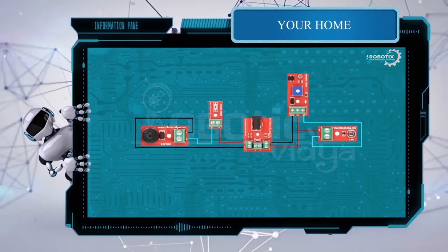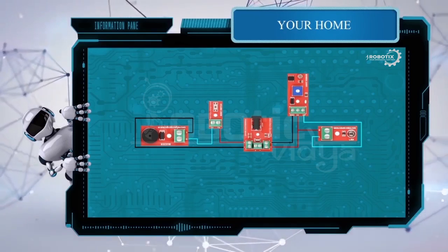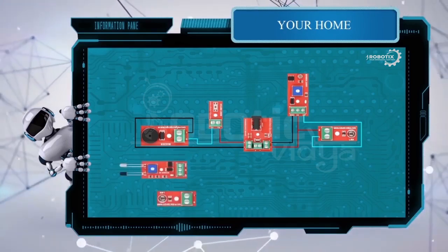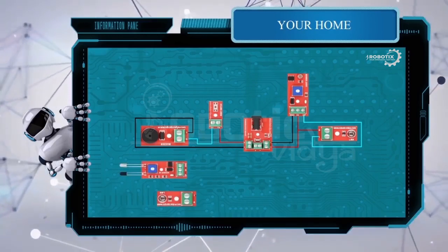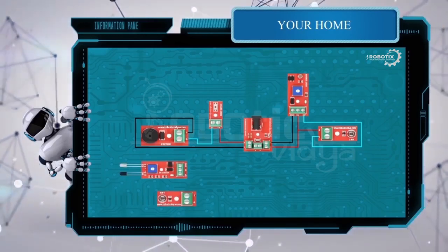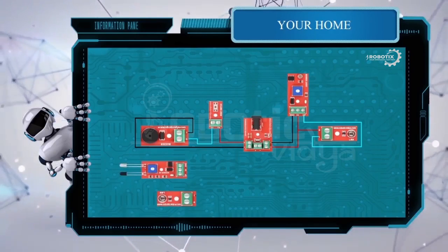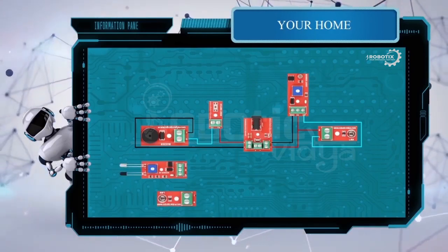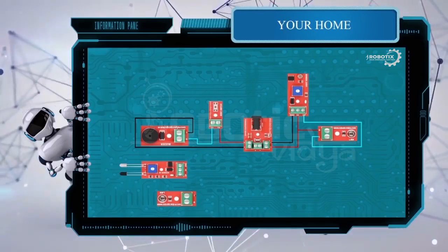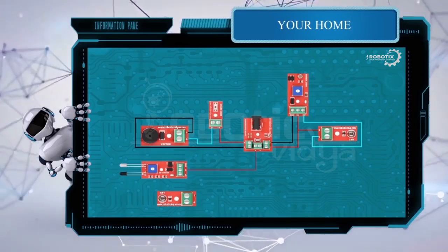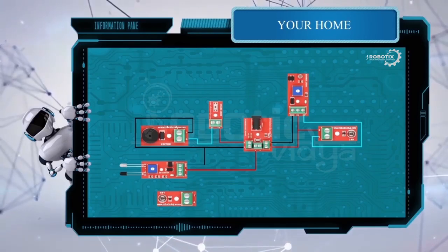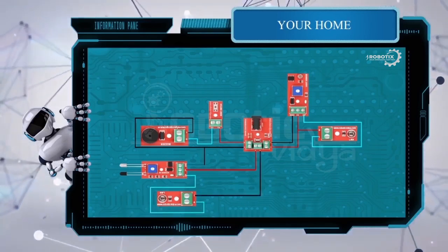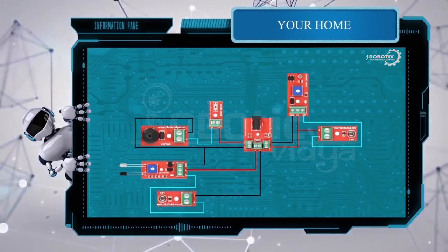The next one was your presence lighting. So this requires that infrared sensor and your LED. So mount both of them onto your project maker, and once done, we shall see the connections. Positive of your power supply board should go to the infrared sensor 5 volt. The negative should go to the ground of your infrared sensor, the output to the plus of the LED, and the minus of your LED should go to the minus of the power supply board.